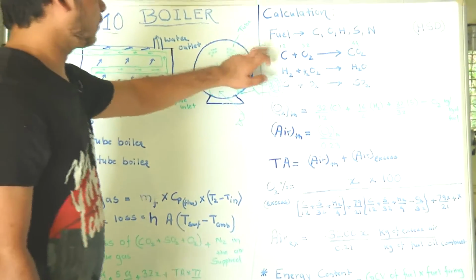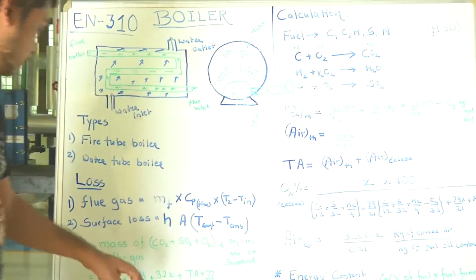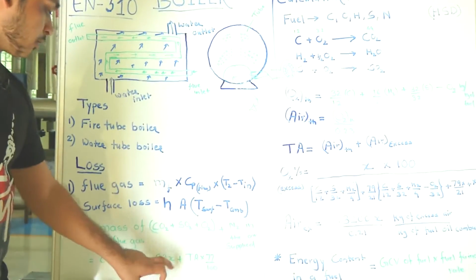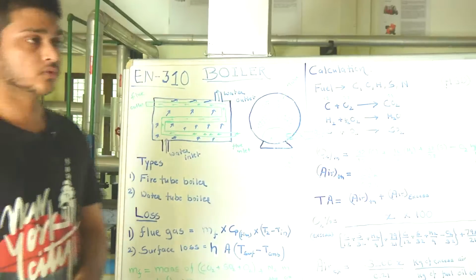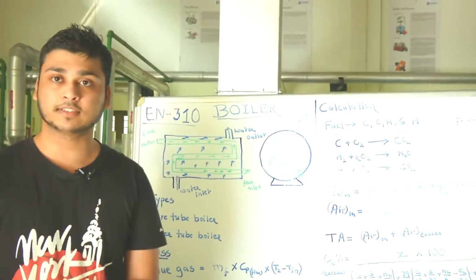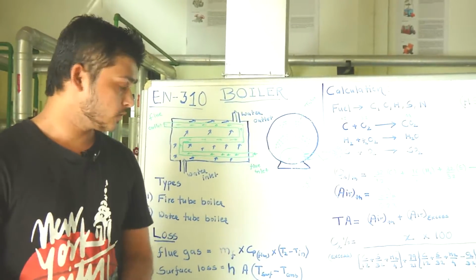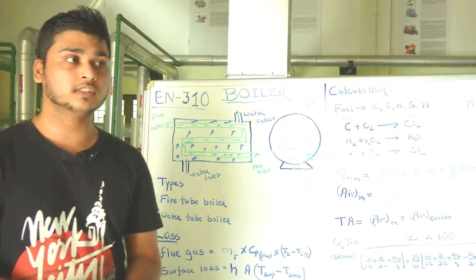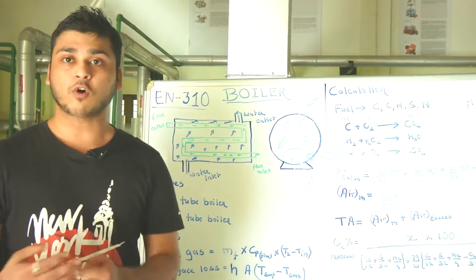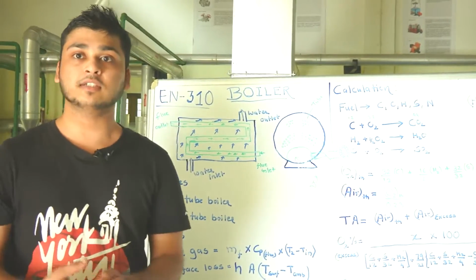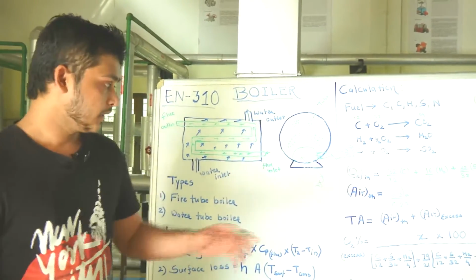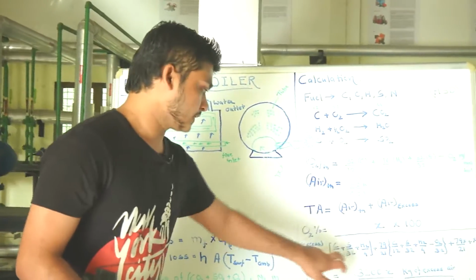Second thing, the calculation of X, because we need X here because of excess O2. With the help of the oxygen sensor, we will get the excess O2, and with the help of excess O2, we can calculate how many kilomoles of oxygen are present in the exhaust gases. So in this formula we can use this.